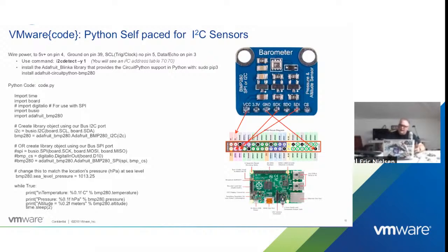So again, easy Python code to just go read the sensor, but you're using a library that you downloaded for that sensor versus the motion sensor. You didn't need a library. You're just looking at the pin and seeing whether it has voltage or it doesn't have voltage. When you're using a bus protocol sensor, you have to talk a bus protocol. And also, because it's usually a more complicated sensor out on the bus, it'll have a chip, which means you're going to have a library that supports that chip. So yeah, that's how that works.